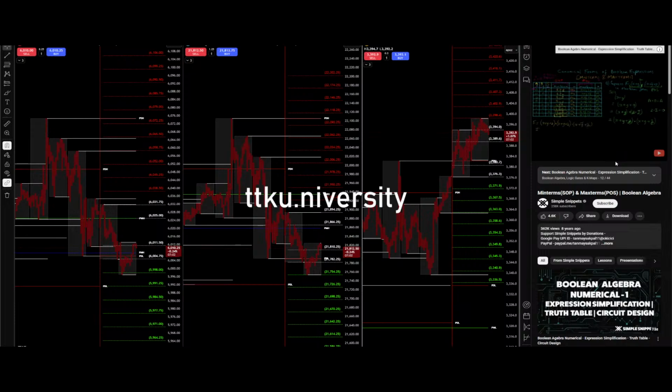Now to represent it with these denotations or designations, I just need to find out where these values belong. So I can see here I have written x, y, z. So I can represent this with M0. Now I need to compare this with this table, and I can see that it is represented as M1, this part. For this term I have M3, so I write it as follows. So yes, this is the canonical form of max term.